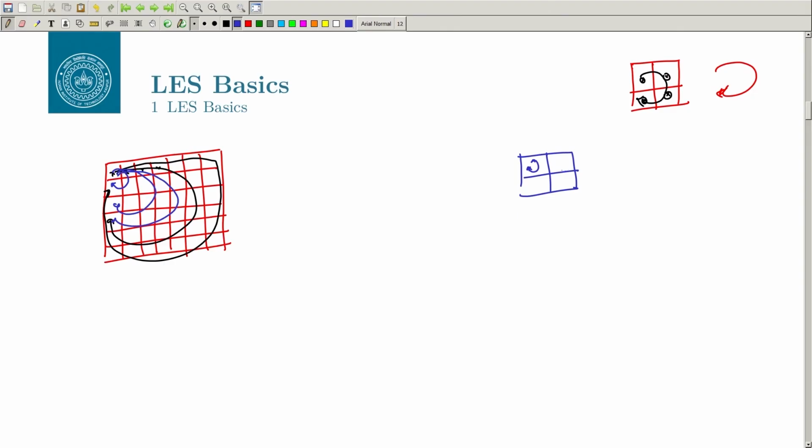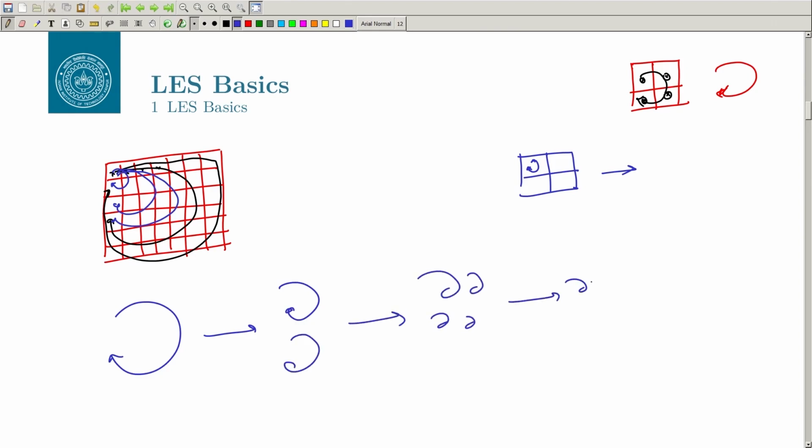So, in this particular case, if this is not up to your Kolmogorov scale, right, it is not going to dissipate, right, because the dissipation happens at the Kolmogorov scale. So, what happens is that these eddies are very unstable, right. So, you have a large eddy, okay, it will break into smaller eddies, and then further smaller and smaller eddies, and so on and so forth, and finally they dissipate, okay, they convert into heat, right.